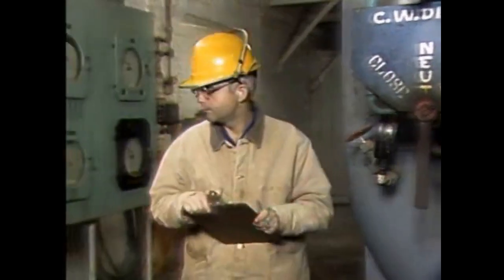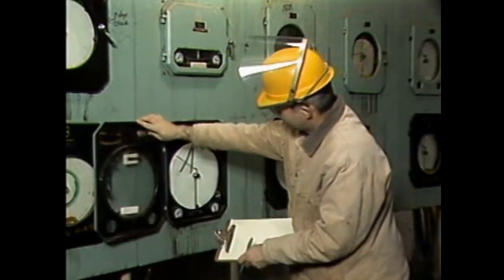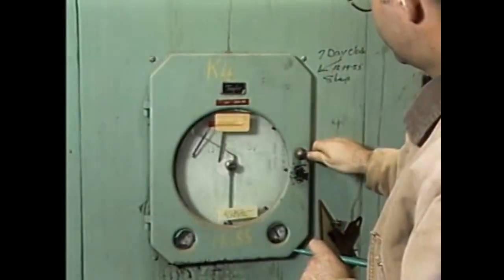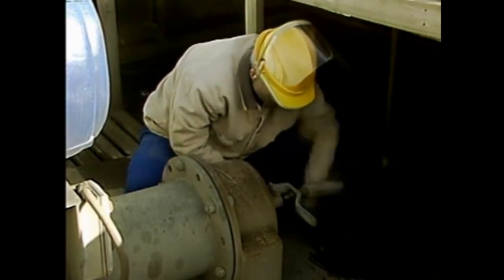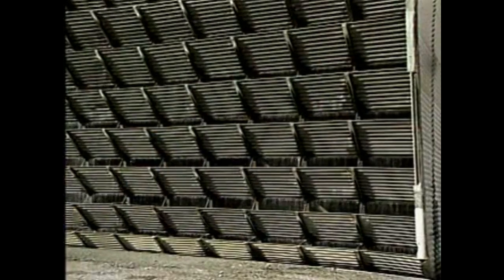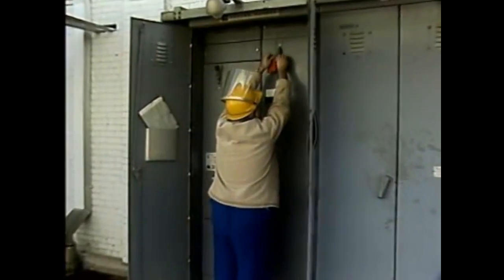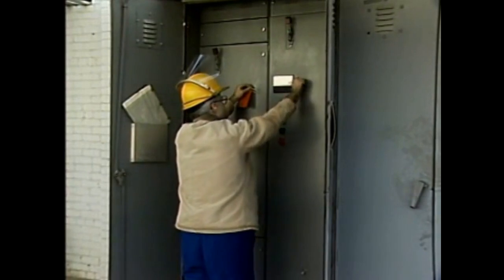Once the cell is shut down, the operator monitors the operation of the cooling tower to ensure that the cells in service are properly cooling the water. When the operator is informed that additional cooling is needed, he begins the startup of the cell. First, he opens the valve on the inlet line to the cell's trough. This fills the trough with water, and the water starts to cascade through the cell. Then the operator removes the tag from the breaker, closes the breaker, and restarts the fan. Once the fan is up to speed, the cell is back in service.